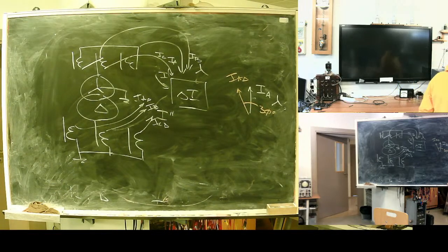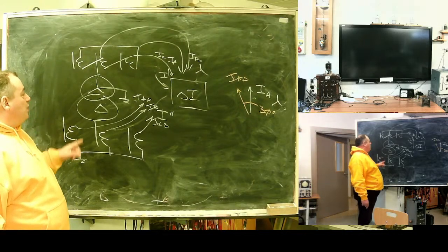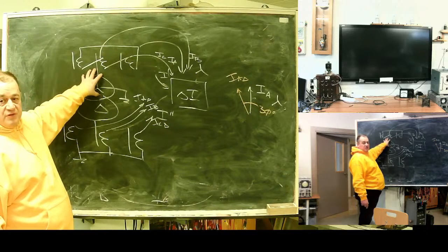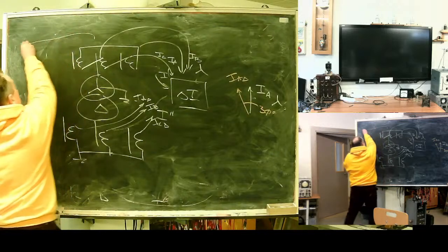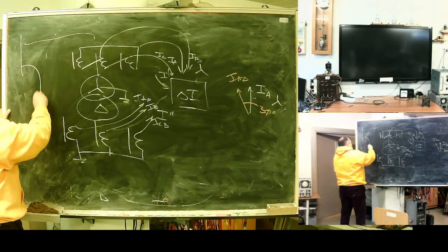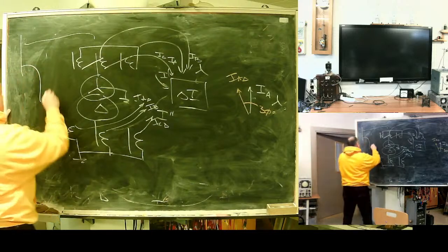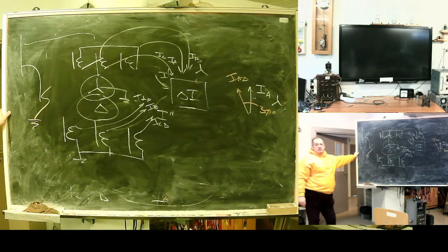Also, it's a very rare trick to make this protection immune to ground fault. There can be a problem. For example, you have a transformer here, yeah? It's grounded. If, for example, you have a fault, ground fault, on some different line, where will zero sequence go?